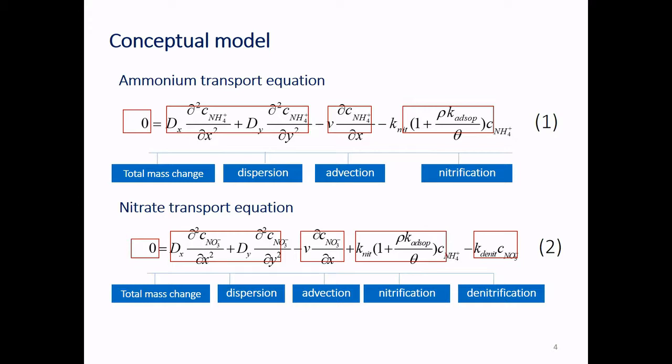But for groundwater, this is challenging because this is 2D. You see we have X, Y as we discussed before. We're simulating a 2D transport. So if we're solving these two equations separately, it's gonna take a lot of memory and disk space, especially memory. We save everything in the memory of ArcGIS, and by the way, ArcGIS only manages 2 GB of memory. You cannot have a large data set take over the entire memory. You're gonna get a very slow run. So we have to think about something more efficient to solve these two equations.